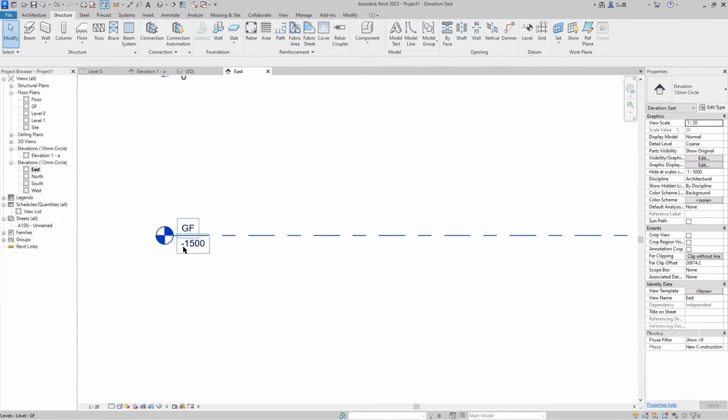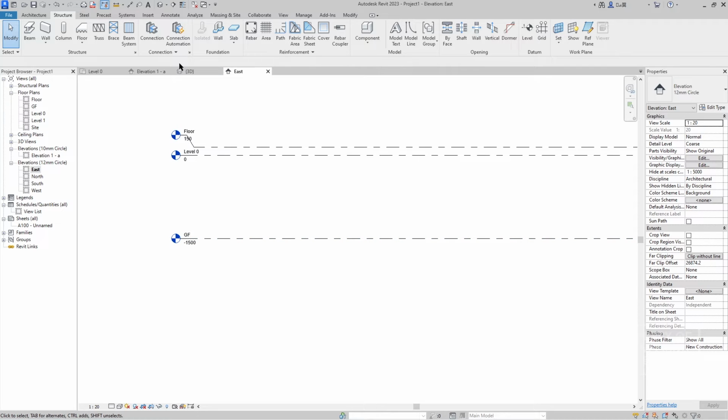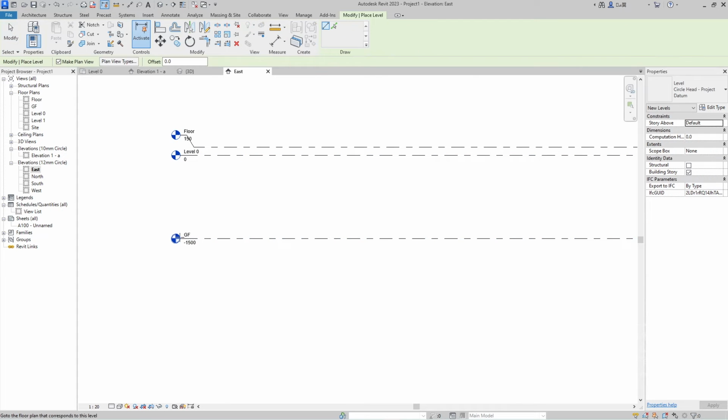Yes, exactly, that's what I need. Oh no, it should be from the floor to level 0, and after that from level 0 to 1500 we're gonna use an isolated foundation. I think I need a new grid here, a new level. I mean, we take it 200.